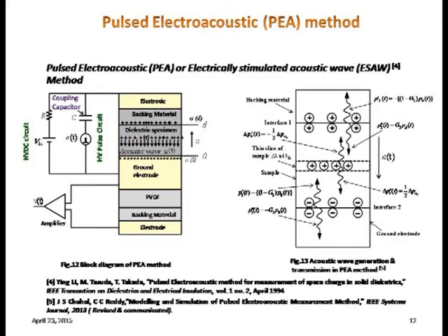This kind of phenomenon is known as charge packet formation, and it happens in LDPE above about 100 kilovolt per millimeter field strength. So this we want to investigate.